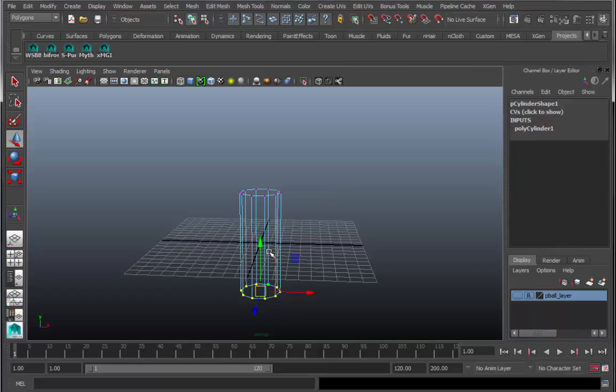So what I'm going to do is hold down the X, and yes, I can do this in perspective view as well because I live dangerously. Hold down the X because this will pop it onto the grid. I'm going to grab the arrowhead of this arrow, keeping it only in that axis. So when I click, I now snap it up to 0, 0, 0.